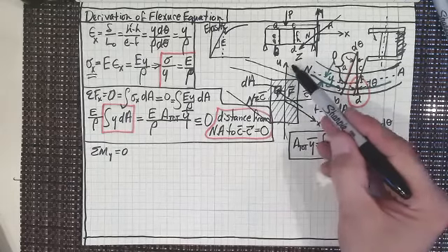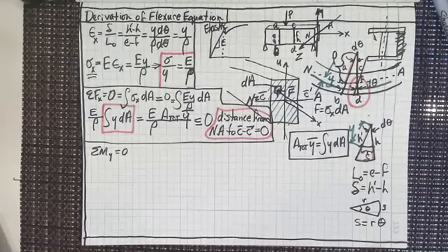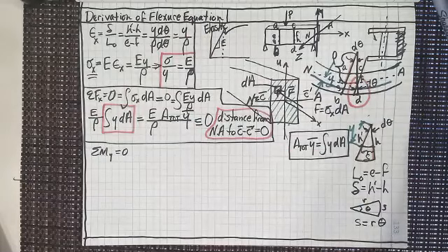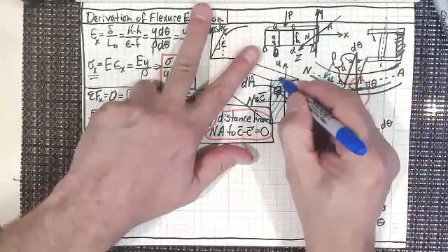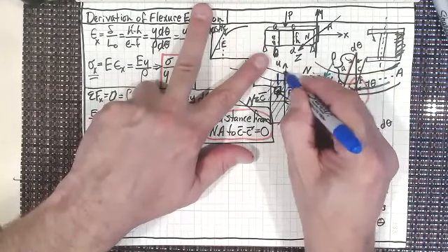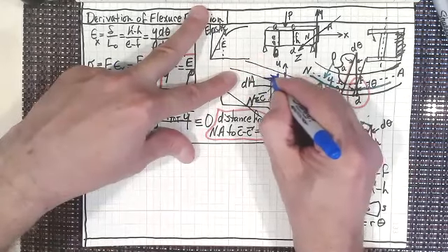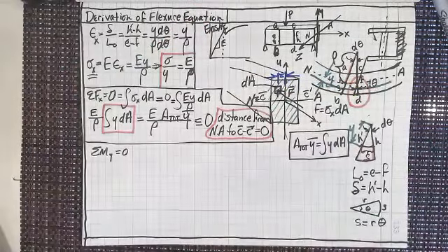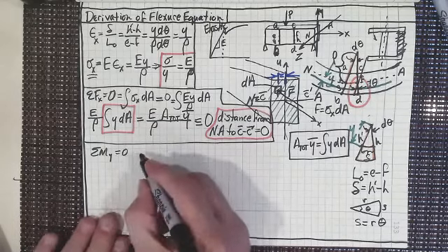What's the distance from the y-axis along this cross section that I've got? I should use another pen color. I'll use blue. What's the distance? So the distance is going to be this distance, isn't it? About the y-axis. Isn't this perpendicular to the y-axis? That would be the distance that we look at, and that would be z. So when I'm looking at my moments of inertia about the y-axis, it's really the distance z.